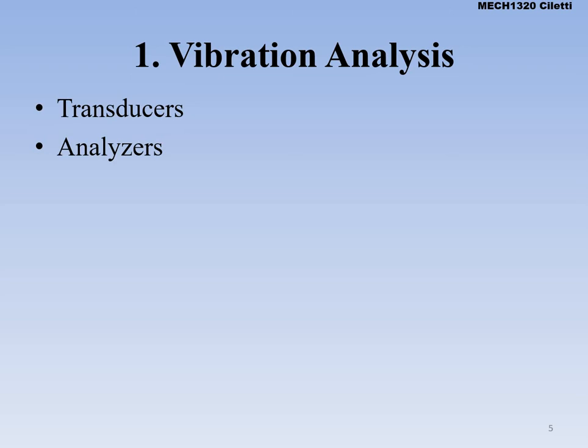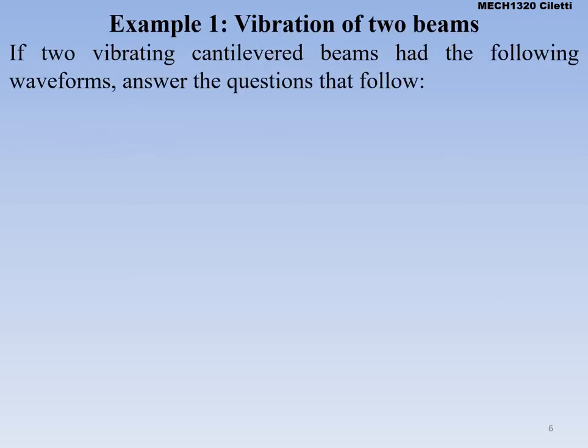And based on that waveform, we can put it into something that analyzes that waveform, and this goes back to how is that motor or whatever we're looking at operating in normal conditions and how's it operating now? So it can do a comparison, and based on that comparison, it can send an alert signal to us. Hey, something's off here. Something's wrong with this particular motor, this conveyor, or all the different things. It doesn't just have to be those, but those are common things that oscillate and make vibration.